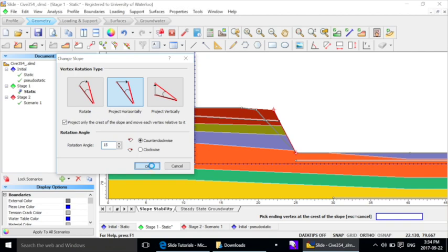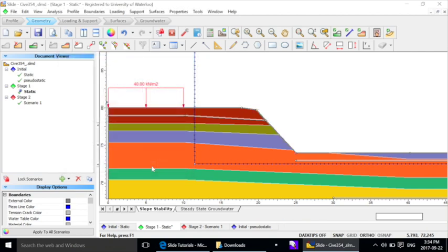And that is what you're going to do. That is all the project. Just play with the options for the inclination of that slope. Then once you accomplish the factor of safety, 1.5 for static conditions and 1.1 for pseudostatic, then go for the second stage of the excavation and repeat the process. Do the same.